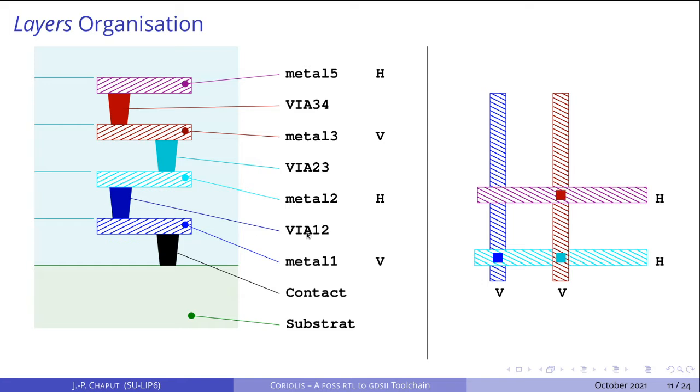The metal layers are then organized in preferential routing directions that you can see on the right side. The metal 1, for example, is in the vertical direction, then the metal 2 in its perpendicular, that is horizontal, then metal 3 vertical again, and metal 4 horizontal again. So this is crisscrossing the design. This is called Manhattan routing, for those who may not know already.